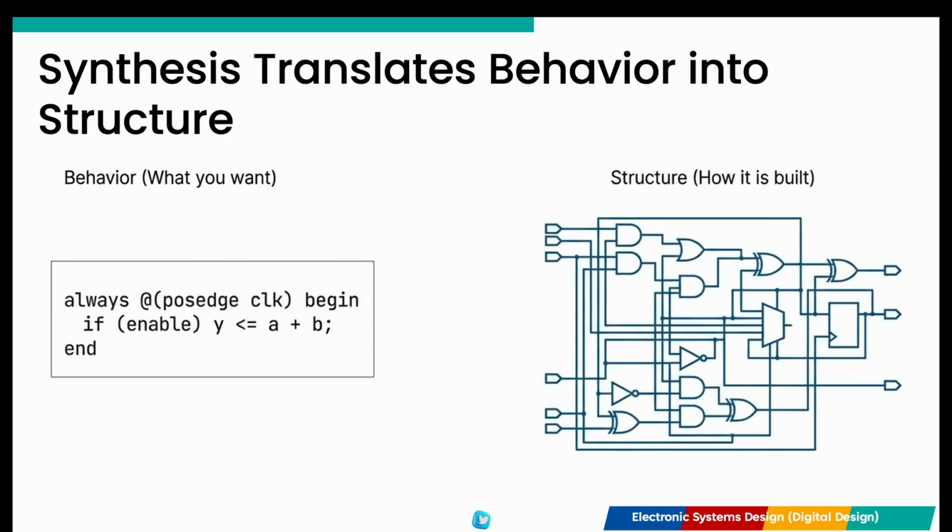The direct output of the technology mapping is the gate-level netlist. This is typically a lower-level Verilog file or an EDIF file. It is no longer high-level behavioral code, rather it is a physical hardware blueprint that details exactly how the actual logic gates, multiplexers, and registers are wired together inside the FPGA. The netlist is incredibly useful because it can be used to run a post-synthesis gate-level simulation to verify that the newly optimized hardware still maintains the exact functional behavior you intended.